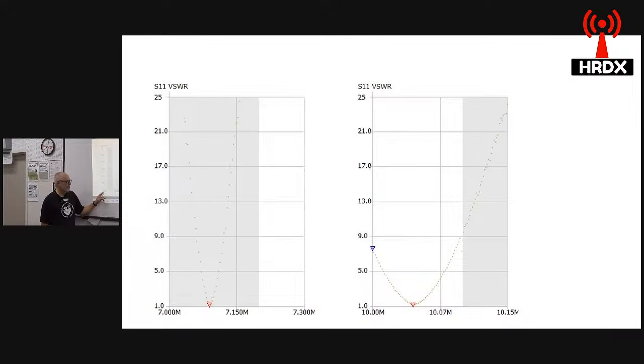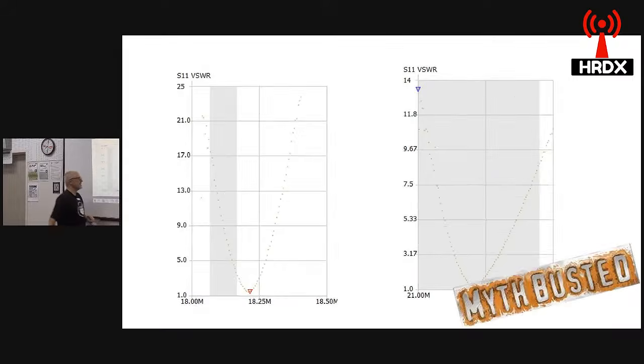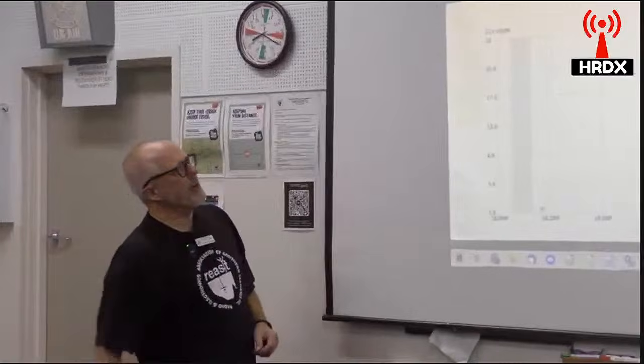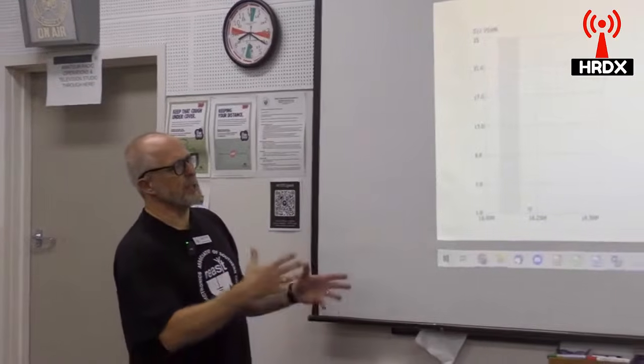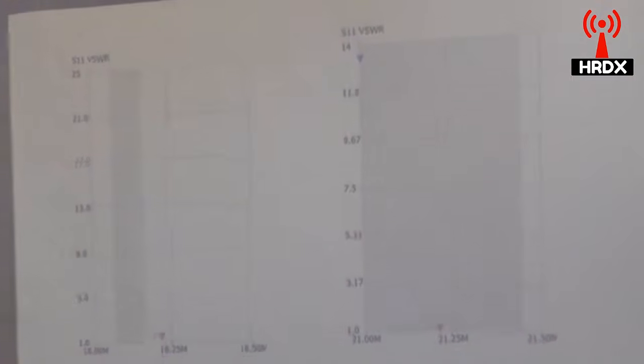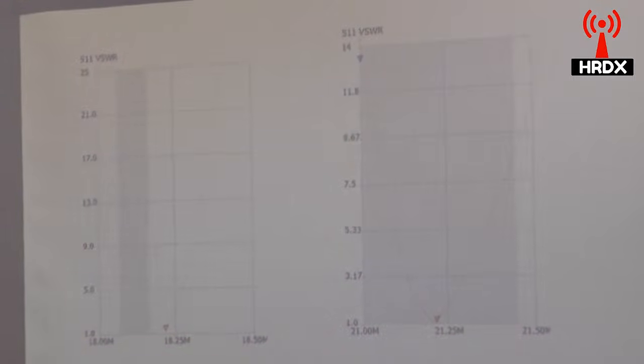18 megs. Now, this is the same scale. I got this the right scale. But you'll notice as we go up in frequency, bandwidth is increasing as well, because that loop is actually going quite wide. The 300 odd sample points is showing that as we go up in frequency, the bandwidth is getting higher and higher, which is what the design specifications were telling us. So that's a demonstration of it.